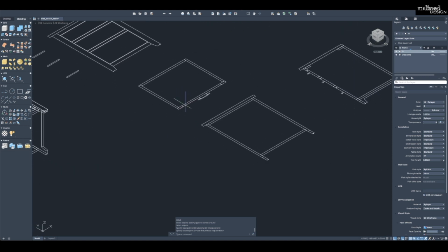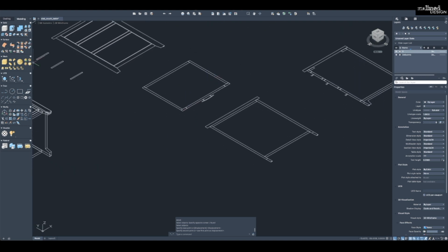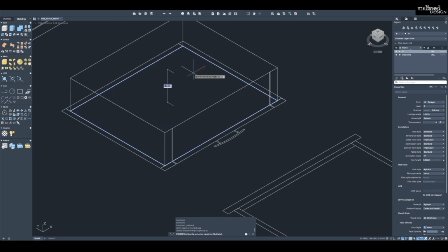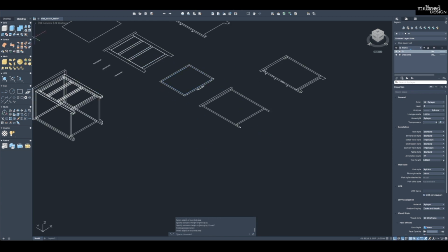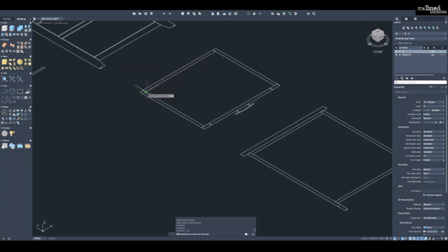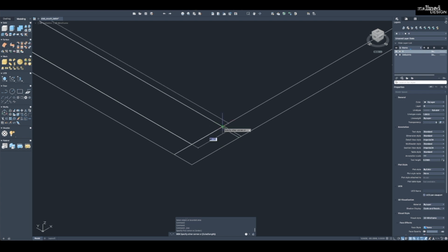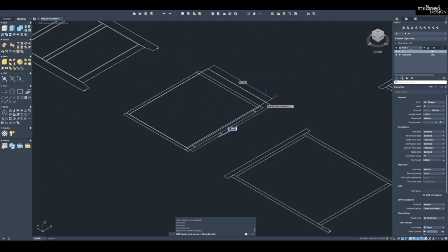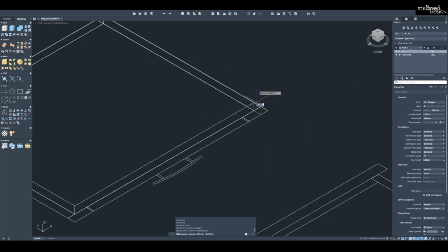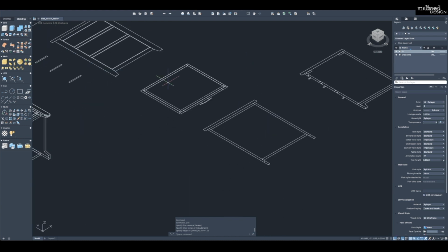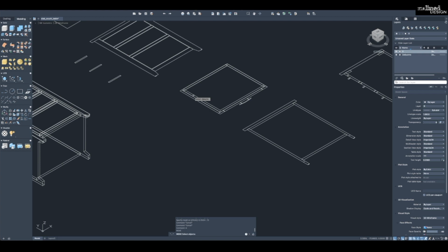And then we just need a floor. And again, press pull command. Because I have a section here, see, I don't like that because we're getting that line. So just go to solid. So it's giving us that funny line because this line is not a solid line. So it's bringing it in the face. So 0.75. So I just use the drawing itself as a reference.